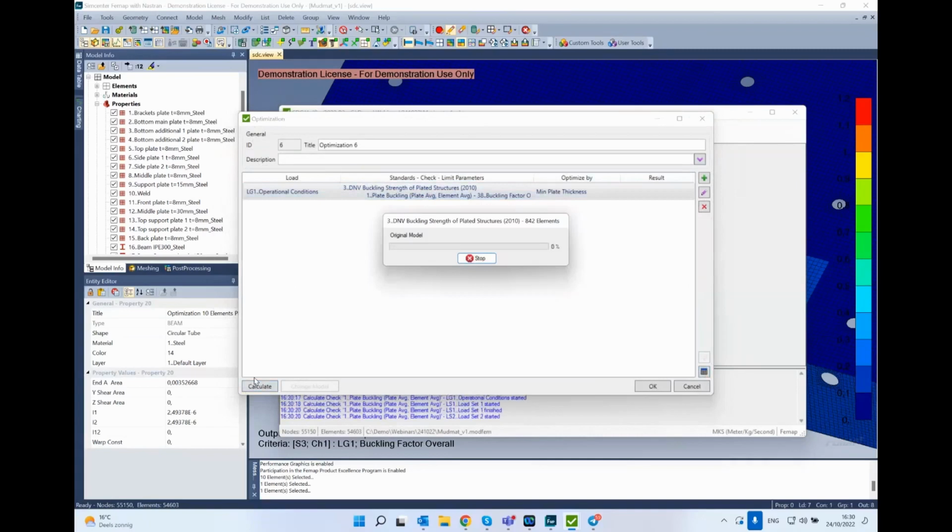Anyway, it's another minute. While we're doing this, I will explain to you once again, and we will go through that after we update the results, that SDC Verifier is not changing the force distribution in the model. SDC Verifier is not changing the model in this case. We are just mapping the stresses or the forces. In case of beams, it's forces.